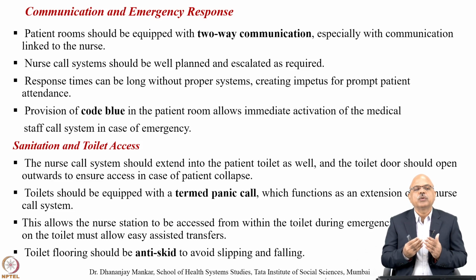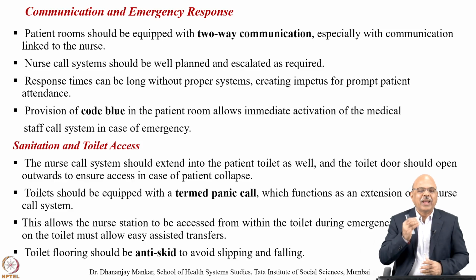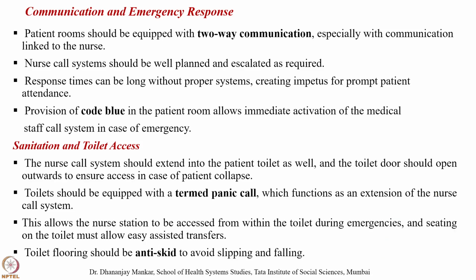Your staff need to be well alert and skilled for the support of code blue installation. Sanitation and toilet access. The nurse call system should extend into the patient toilet as well, and the toilet door should open outwards to ensure access in case of patient collapse or if the patient gets a major injury in the toilet. The toilet should be equipped with a panic call, which functions as an extension of the nurse call system, where the patient sometimes may panic in the toilet.